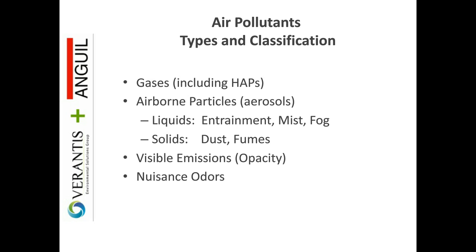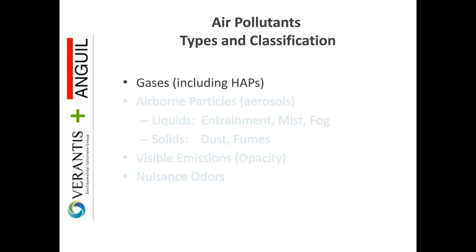HAPs include certain VOCs. They also include the various inorganic acids that Scott mentioned that can be formed as a natural part of combustion of certain contaminants. Wet scrubbers are also used for various particulate applications, both for just reduction of particulate and also for specifically reduction of opacity or visible particulate coming out of an exhaust stack, as well as all sorts of odor applications. But as far as thermal oxidation goes, the real focus is inorganic acid production.